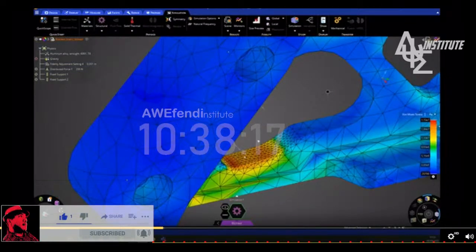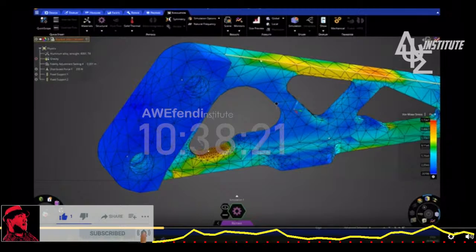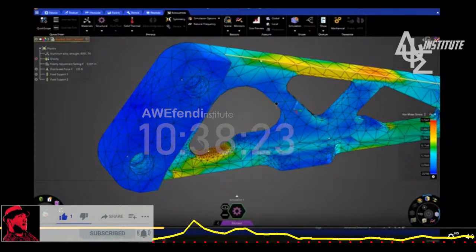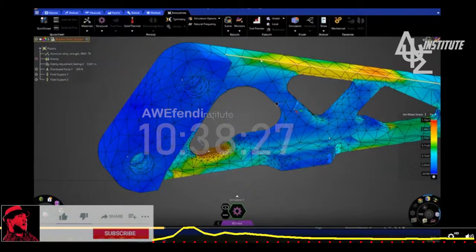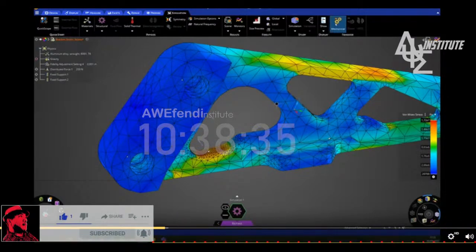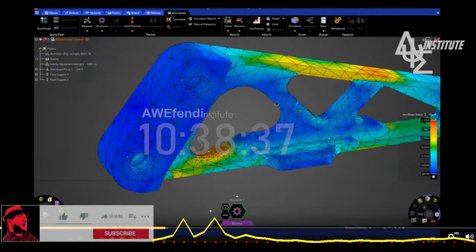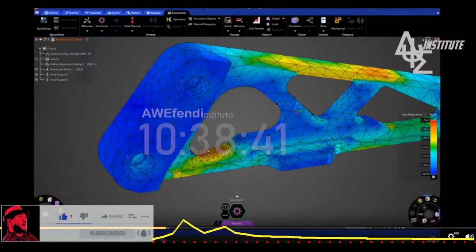Another cool feature that we have over here is if you want to define a better mesh, or you want to use the features that are available in Mechanical after you've done an initial analysis with Discovery, all you have to do is click on this button over here, and you can see that it transfers immediately to Workbench. Okay, now let us move back to our slides.